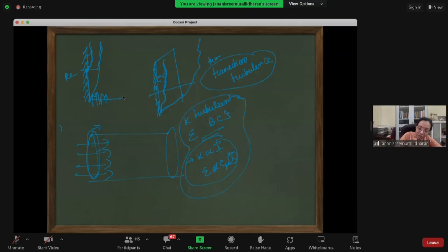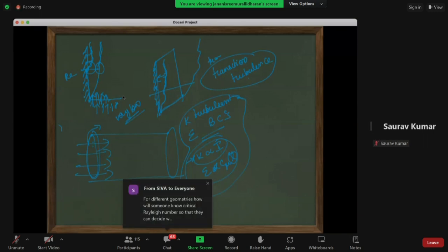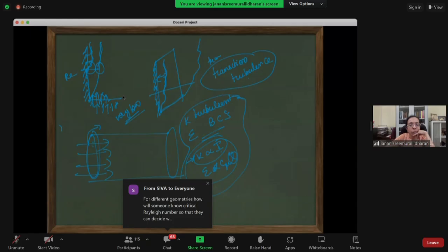Now, in these models, you might still have to specify some inlet kinetic energy. But when you calculate with the K and I formula, it will be very low, and that is fine, because these models are built not to take turbulence from here, but to view the Re and then switch on the turbulence model. Am I clear? Yes, ma'am.